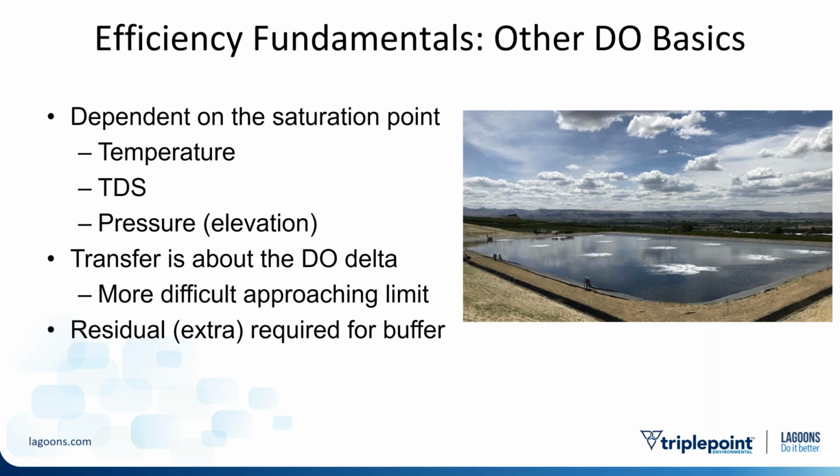The DO delta, like where we are now and where I want to get, is also pretty important. So basically what it comes down to is water with no DO is much easier to transfer oxygen to than water with 10 DO. So it's easier to transfer oxygen at lower dissolved oxygen. If we're trying to run a higher buffer oxygen transfer content or dissolved oxygen content, it's going to require more energy to do that.